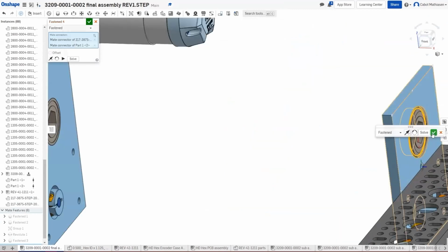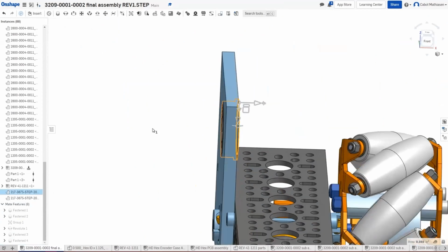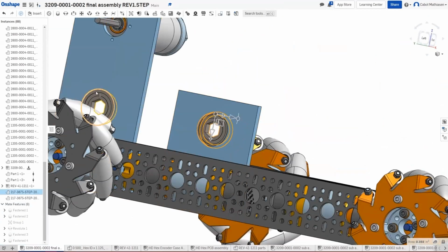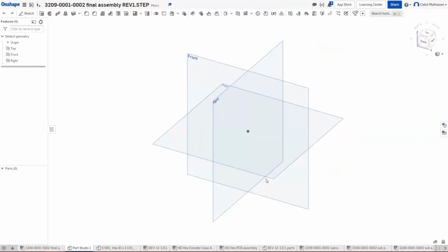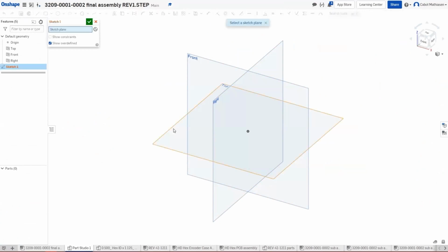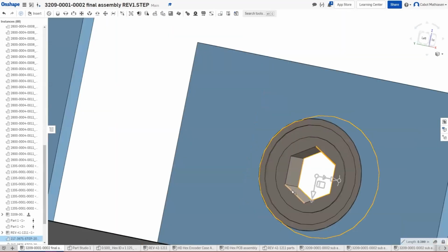Now we're measuring from the farthest out parts of the bearing because we need to make a custom designed hex shaft. You can just buy a longer one and cut it off. I'm just doing this for the part. Now I'm going to make a new part studio. I'm going to make a custom hex shaft. We need to design the hex pattern. Doesn't really matter which one you use because we're going to be dimensioning it in a different way. So I'll bring it down to 6. And then as you can see, it's 0.5.